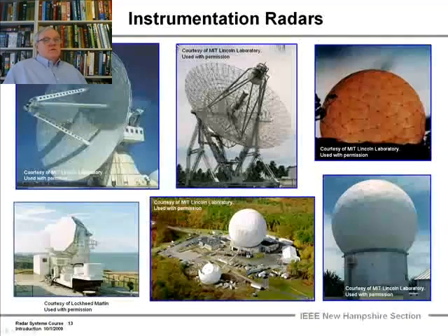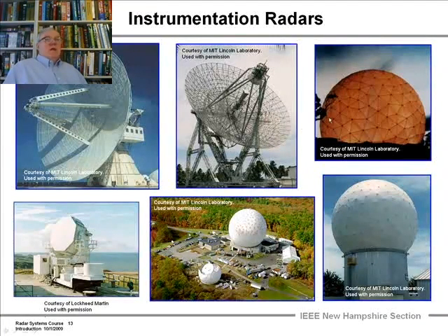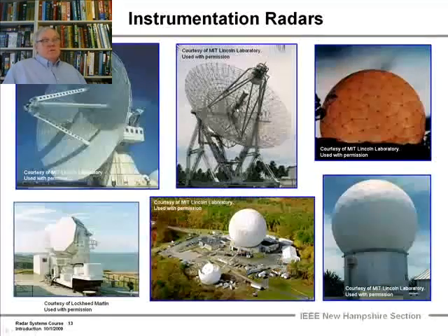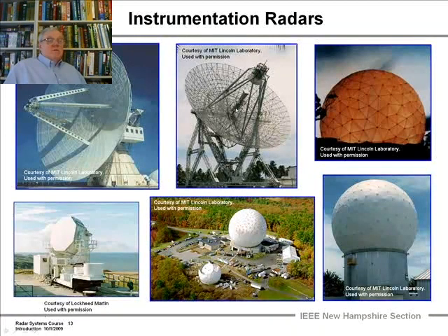Here are a bunch of radars, these four, located out on the Kwajalein Atoll in the Pacific, that are used as scorekeepers and data gatherers for missile defense tests. They give you an idea of the frequency range they operate over. This one operates at UHF and VHF frequencies, from 400 megahertz, say 0.4 meters to 2 meters, on two different frequencies. And this radar, inside this radome, has a wavelength of a millimeter, at 35 and 95 gigahertz on two frequencies. It's dual band.